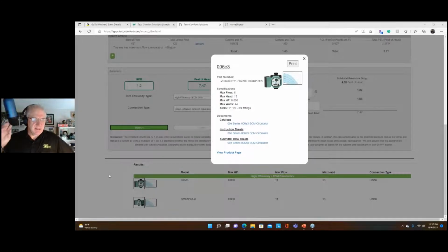The tool does not allow for supply piping sizes above 1 inch. No, this is a residential tool. So thank you for asking that. This is a residential tool, and we are working on a commercial version of this for larger systems, but right now we're just dealing with a residential tool. So it's kind of where we're at right now. There are going to be larger residential applications where maybe you need 1 1/4 inch pipe, and we can see about adding that if necessary. But at this point, we try to hit the big sweet spot of residential applications, and 1 inch was the max.